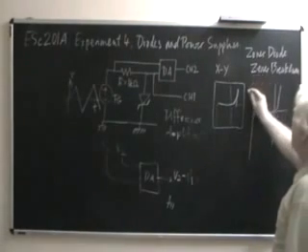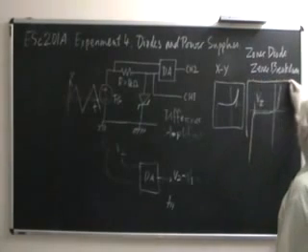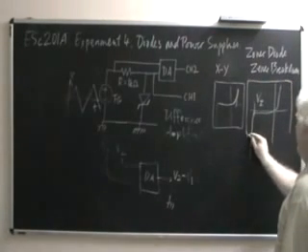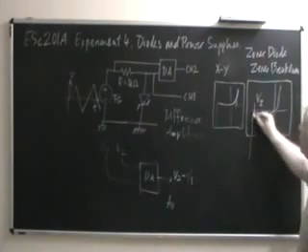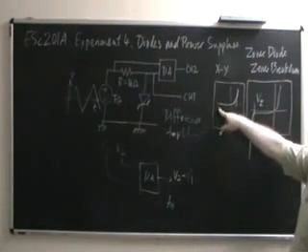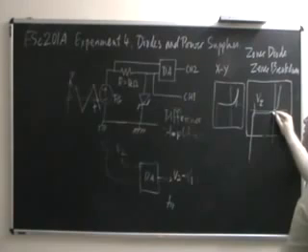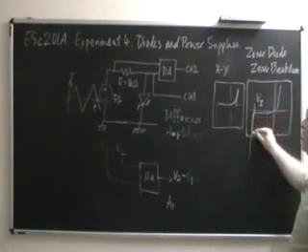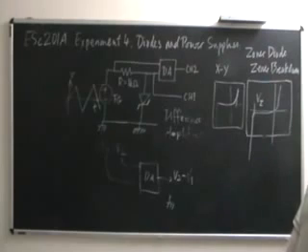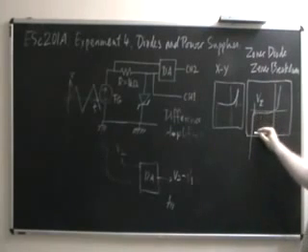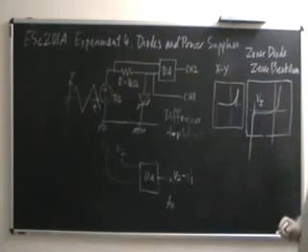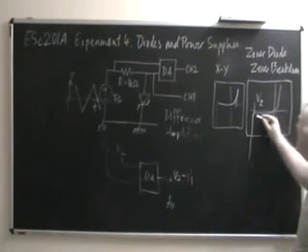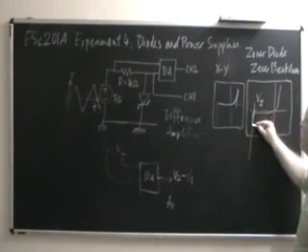then your screen would show you something like this. You would see the breakdown region as well, which you could not have seen with the ordinary diode. You would see this forward part, the reverse unbroken down part, and the broken down part. You can even try to take the inverse of this slope and estimate the reverse resistance of the Zener under breakdown conditions. But the value will be so small that I doubt you will be able to get a very accurate figure. Initially it's slightly curved over here, but then it becomes literally straight.